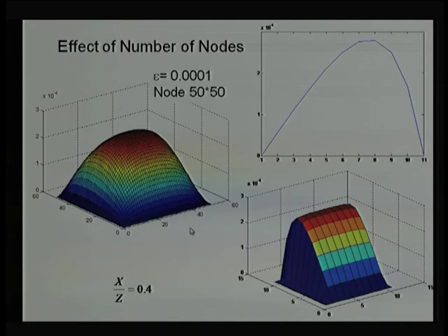Now, why am I emphasizing this? Many times we require complex solutions, a combination of solutions. We have been treating only the hydrodynamic case, where the fluid film varies toward the convergence gap, but many times we need to consider whether there is any thickening effect. An increase in pressure is going to change the viscosity.